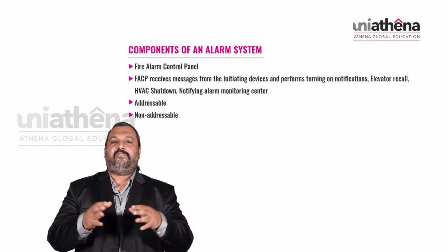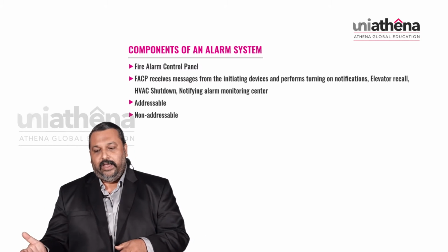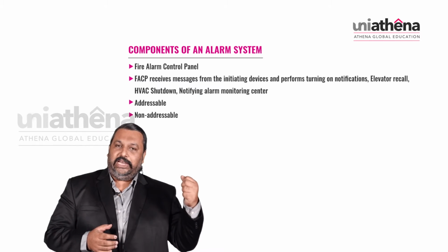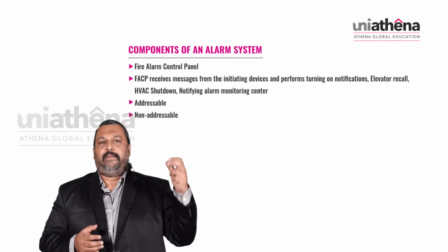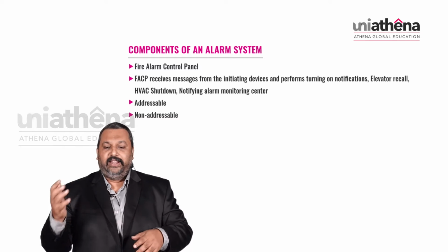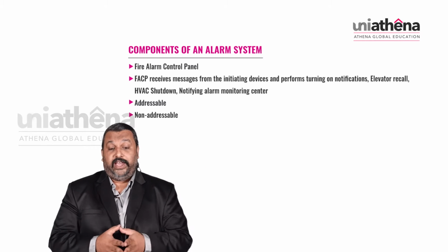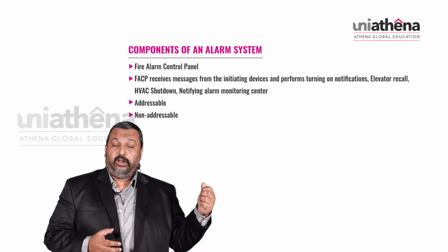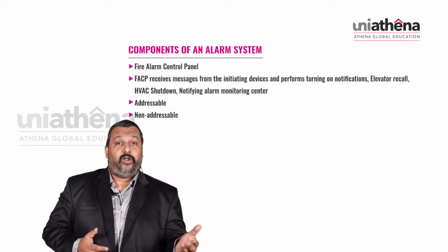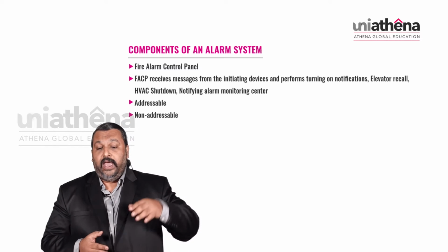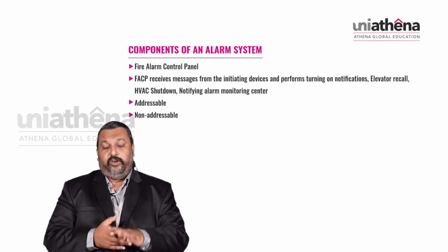So it is like the central processing unit of a computer. It receives messages from the initiating devices that a fire is happening, and then it performs turning on notifications, elevator recall and HVAC shutdown. All the HVAC system has to be shut down, and then it notifies the alarm monitoring center.